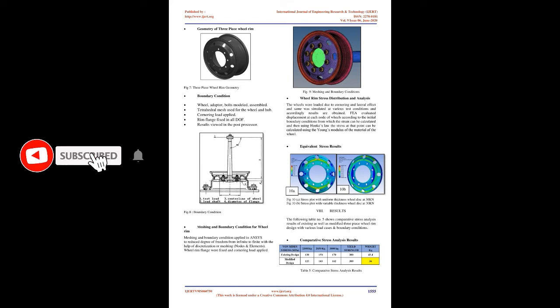Wheel disc thickness increased at the region identified to have higher stress and gradual reduction of material thickness at lower stressed regions. The modification in the design is shown in Fig 5 and 6. Following design changes to be incorporated to reduce rim weight and also simultaneously improve its performance. Increase in nave thickness to avoid crack initiation in the region due to fretting.